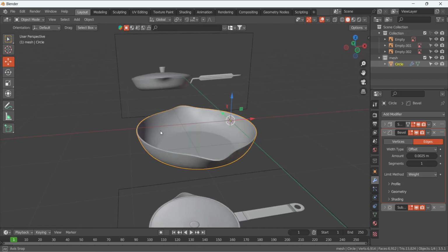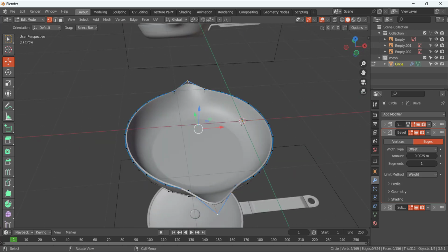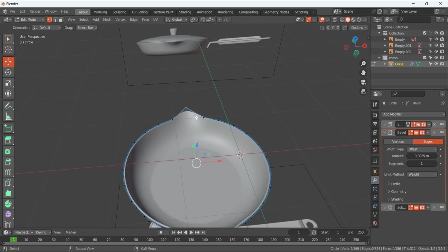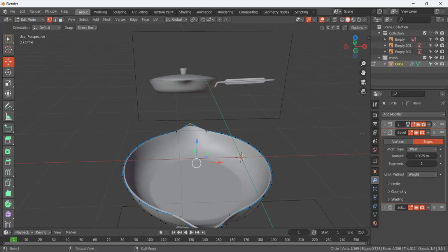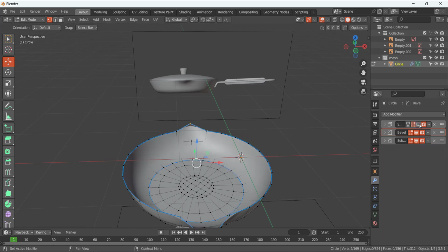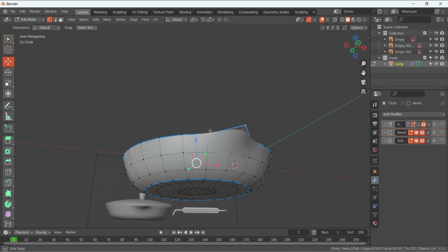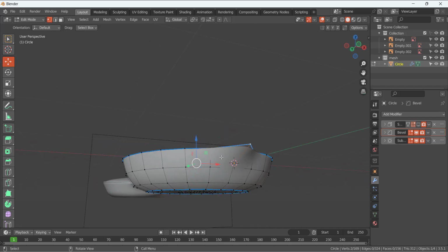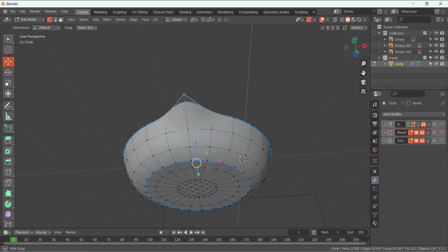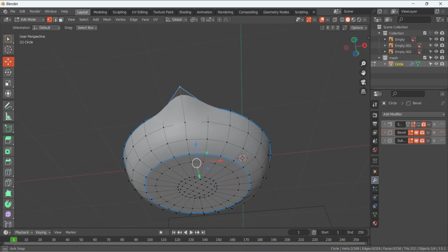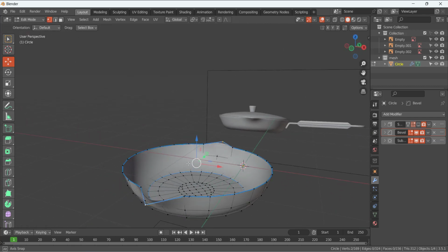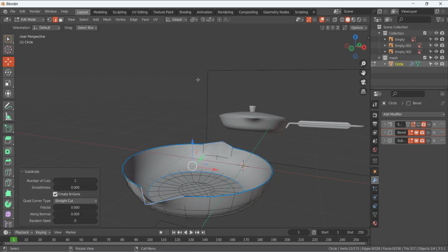and you can see it's looking good, but we have to add a little bit geometry here. And let me undo this bevel, so we can see, so we have a geometry here, but if we add the loop here, it will destroy this circular shape. So we are just going to subdivide this edge, sorry, select this edge, this one, and we are going to subdivide it.